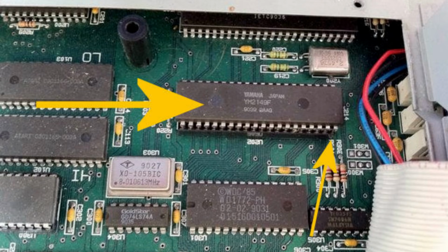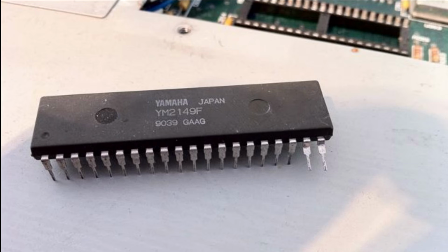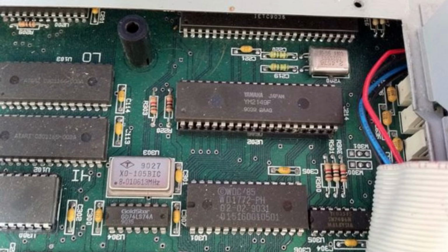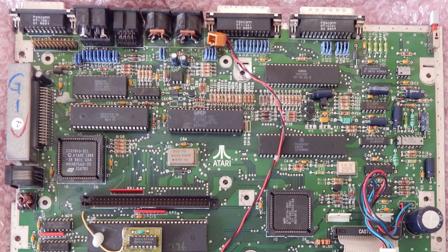20. So if you want to make the external drive an A drive, then you have to invert the signals on pins 19 and 20. You can do this by removing the Yamaha chip from the ST and bending pins 19 and 20 so they don't make any contact anymore with the socket. Then you connect a switch to those pins which connects the signals to the drives. But for this to happen, the Yamaha chip has to be socketed. Otherwise you have to desolder it and insert the socket yourself. And I don't want to do that, and I don't like bending IC legs either.